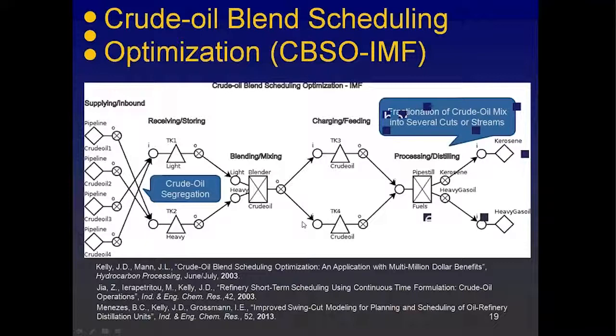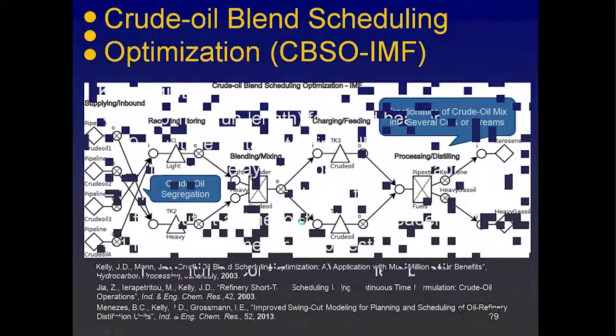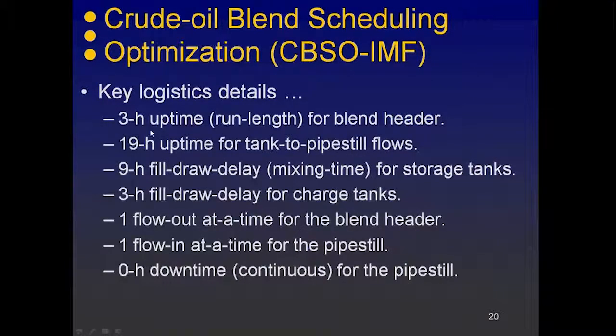managing, I put some key logistics details. So you can have things such as, a nice one here is, when you fill a tank, you can have what we call a fill draw delay. Essentially what it means is, when you put material into a tank, you cannot take material out. In this case, you would configure 9 hours. So you cannot take material out until after 9 hours.